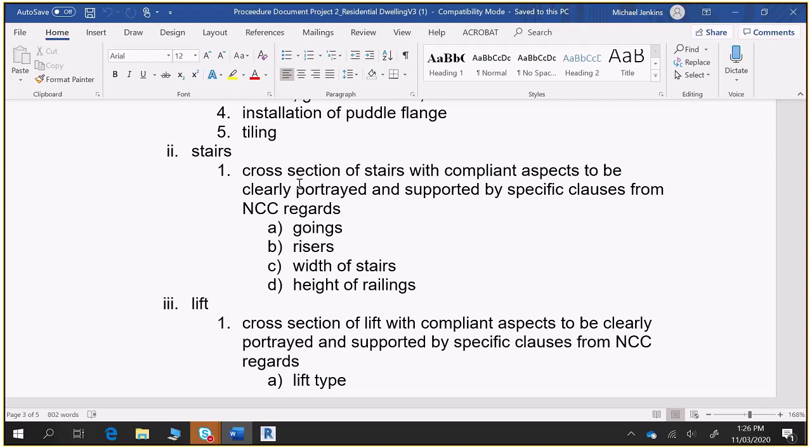What if you do the set down, but you batten out your flooring, and then say use something like timber to take that? Well, that'd be absolutely lovely. Then there's implications for your skirtings all the way around and all your architraves, and then when you enter the front door, you've got to step up. There's always going to be implications. Yes, exactly. Definitely you could do that as well. Yeah, certainly. You could batten out and do.